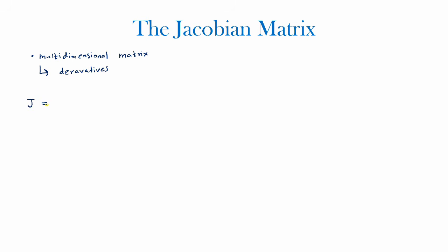So practically the Jacobian is all about the velocity. The Jacobian matrix would be made up of the equations or the velocity vectors. But when we do a question or a calculation, the easiest thing to find would be the position of the joints and the links. But by taking the differentiation or the derivative of this position, we can find the velocity and thus the Jacobian matrix.